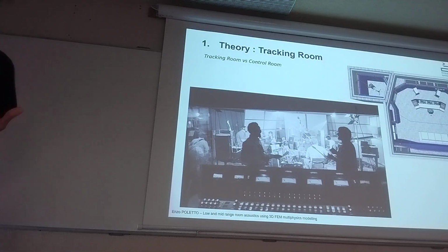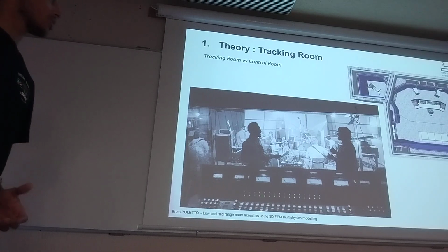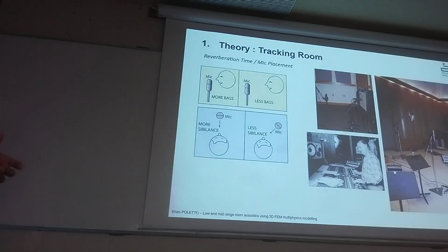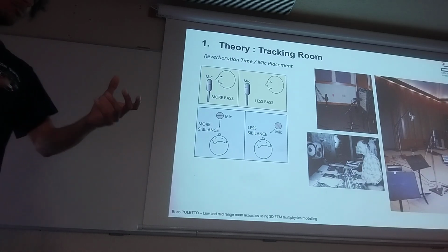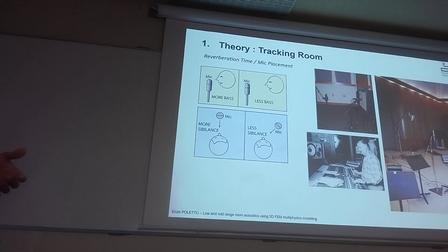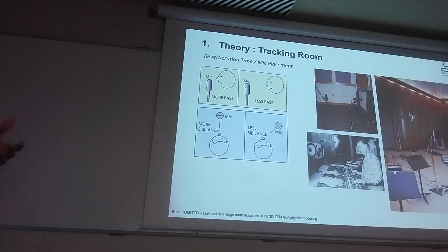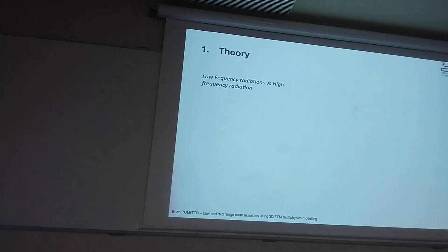So you have the effect of electronics, the microphone you use, the processor you use, but the effect of the room is very important, as important as mic technique: if you're closer to the mic, you get more bass; if you sing off axis, you get less sibilance. But most importantly, how big the room is and how reverberant it is is going to greatly affect the recording. So that's why in a recording or mixing situation, it's important to tweak the room and its frequency response.